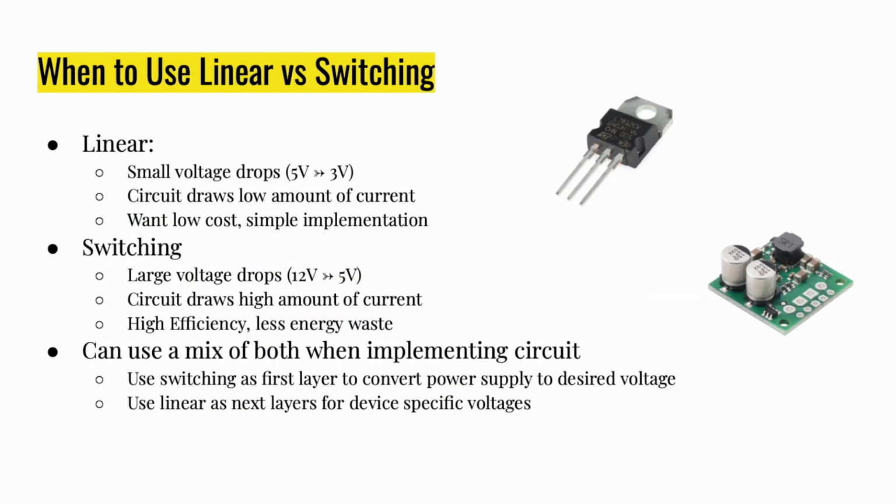So linear regulators are smaller and simpler components and should be used when you want a small voltage drop like 5 volts to 3 volts, or just a low cost and simple implementation on your circuit.